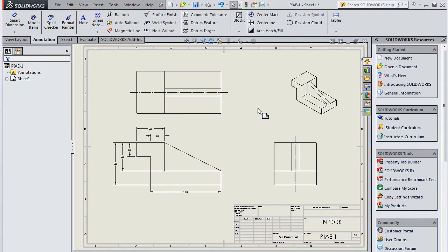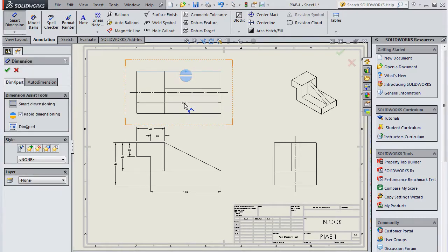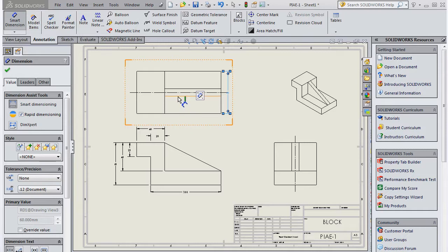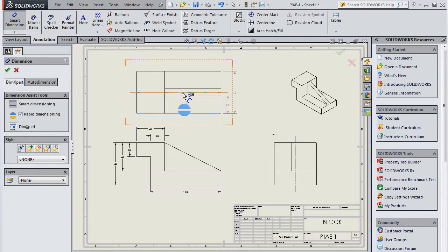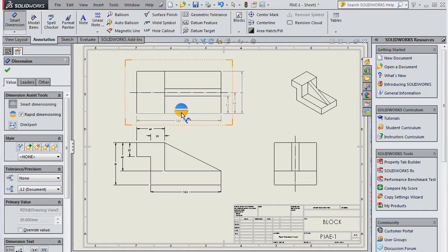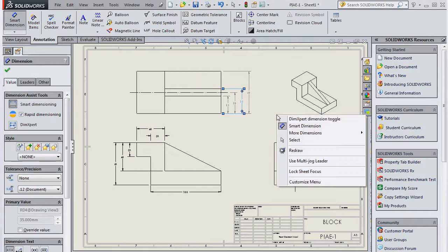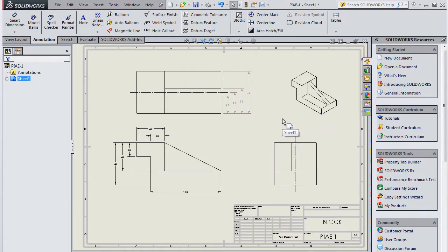While adding dimensions in this manner is the preferred method, the Smart Dimension tool can also be used. To place the dimension, click on one of the blue segments. Dimension positions automatically update to ensure the largest dimension is always farthest away from the figure outline. Dimensions added with the Smart Dimension tool are grey in colour. They are driven or reference dimensions and cannot be altered if you were to double click onto them.